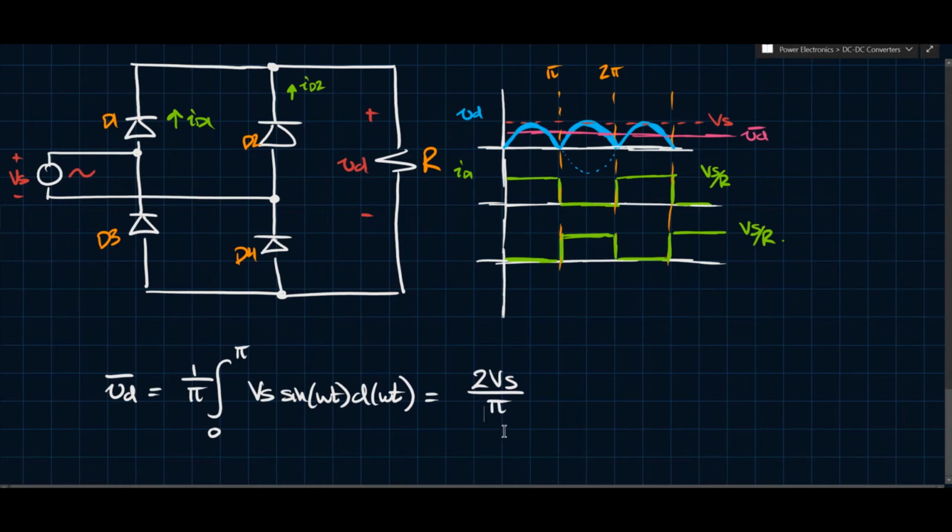And this is now twice what the half-wave rectifier was, which makes sense logically speaking, because we now have twice the output voltage, right? So in the other case, we only had half of the wave. Here we have the full wave, which is obviously twice of half. And so then we obviously expect the output average to be consistent with that too, which is true here, which is nice. So this is a more commonly used rectifier circuit. You'll see this in many electronics applications.